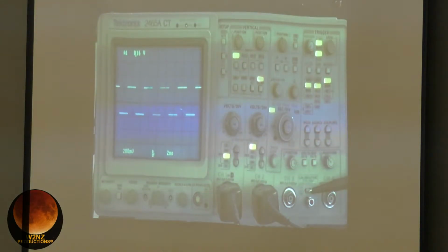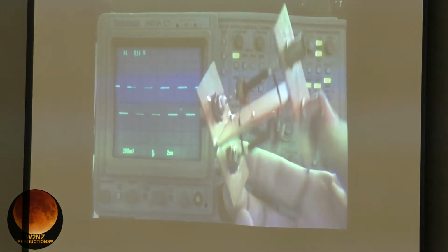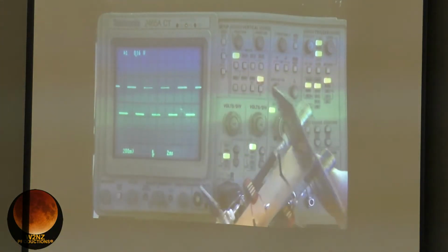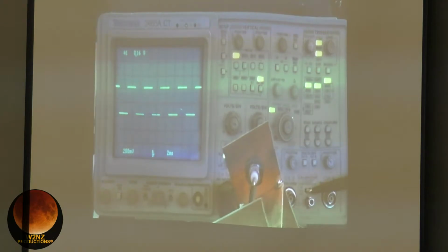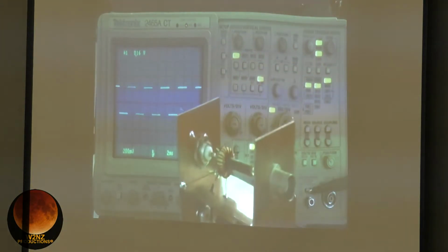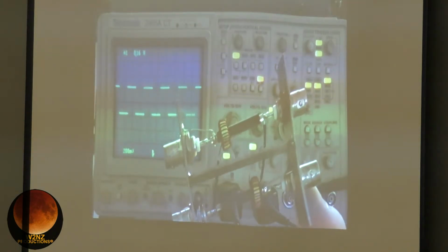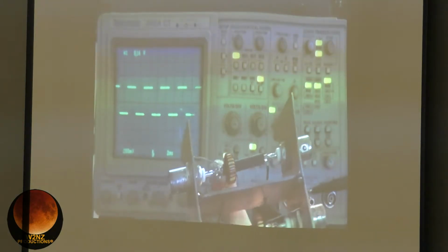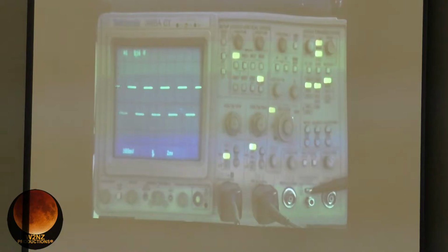Another example is if you build yourself a homebrew directional coupler like this one here. Just a little simple toroidal coil sitting around the coax between your RF path. The bottom is the sampled output. The top is the RF path. There's another way to do that.